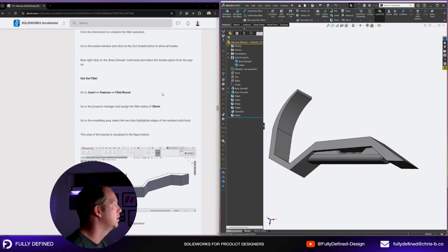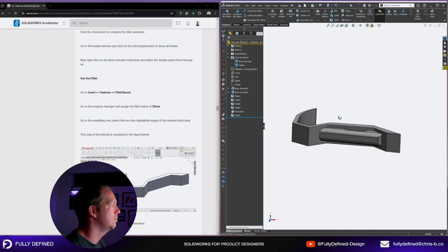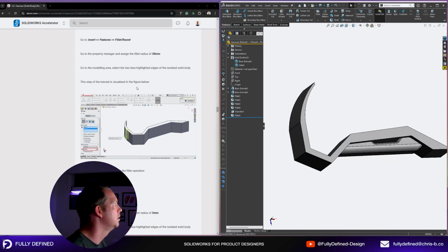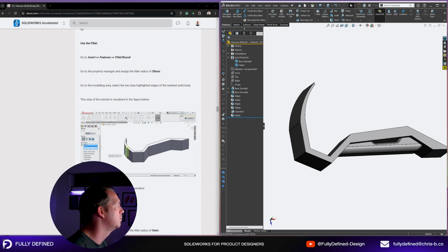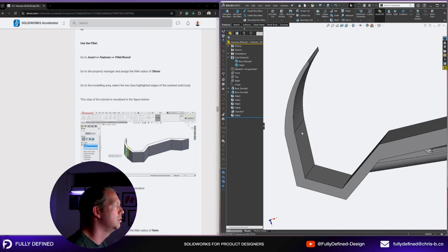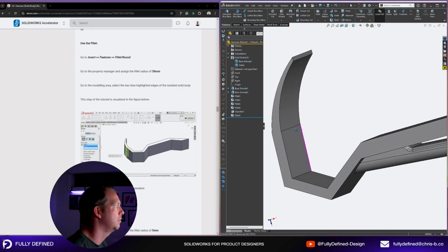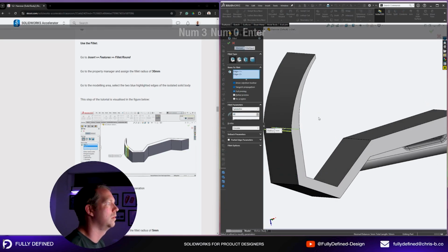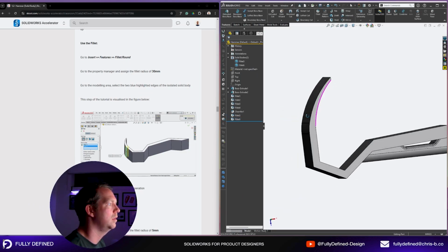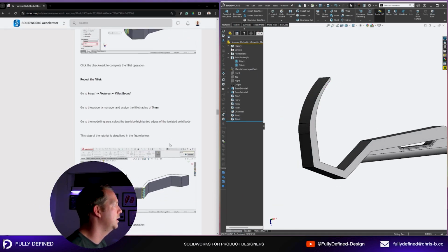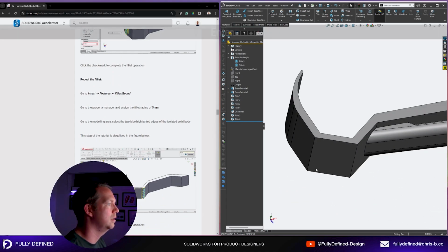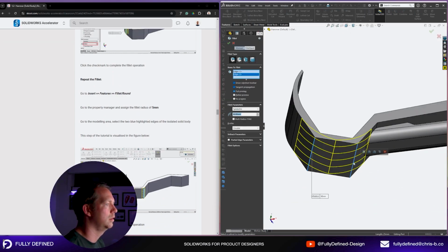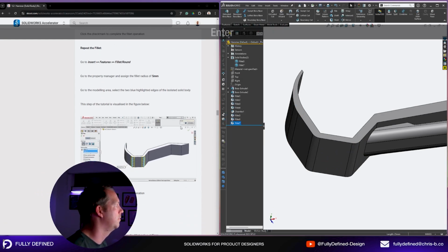That's good. So some more fillets. Let's curl around here. So we want to do 30mm radius on these 2. I believe it's this one and this one. Okay, it's fine. Repeat the fillet. 5mm ones down here.